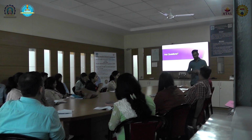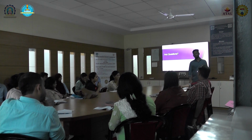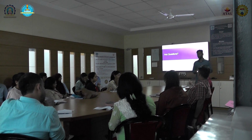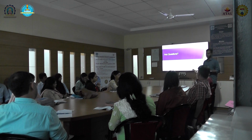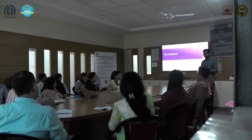The advantage of formal over simulation is that it's fast. Simulation might take 1 or 2 hours to run, while formal will give you a failing scenario in 10 or 20 seconds. But as the complexity increases, the time for formal to find a failing scenario also increases. As you mentioned, cone of influence is related to the depth of formal. As the complexity increases, it is hard for formal to find the failing scenario.